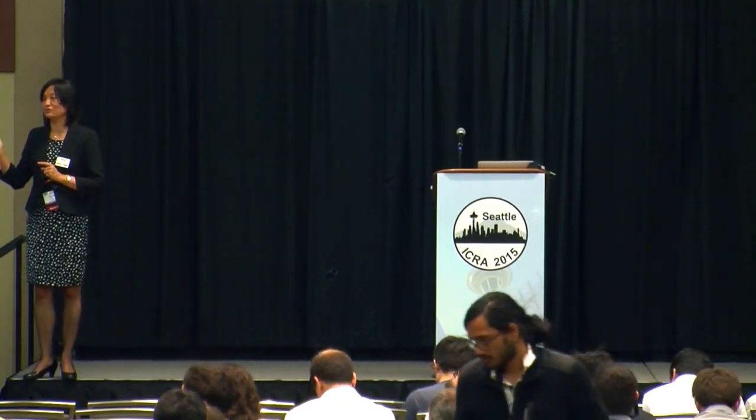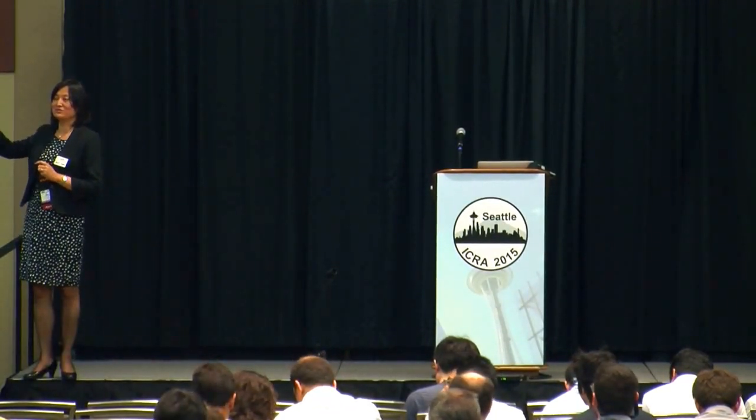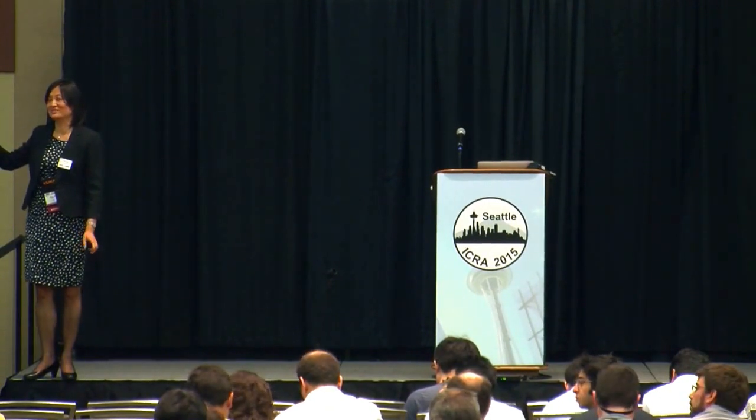Oh, we can go faster. The algorithm is very fast. We deliberately make the robot execute at a slower speed because the robot is open loop. There's no closed loop control for the robot. But for the algorithm and all the simulation, what you see is what you get. Okay, it's still in real time. And for one experiment, the very initial experiment I showed with the grasping, we deliberately made the robot move slower to avoid obstacles and make sure that things are safe. But even that, the speed up is only 1.5 times.